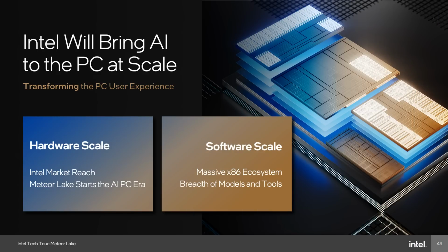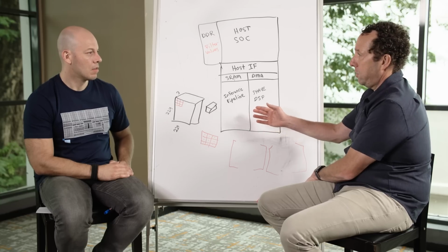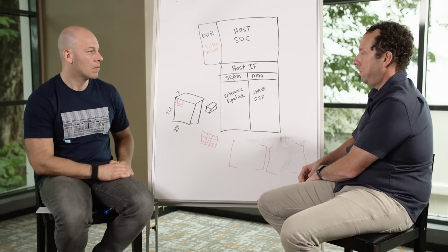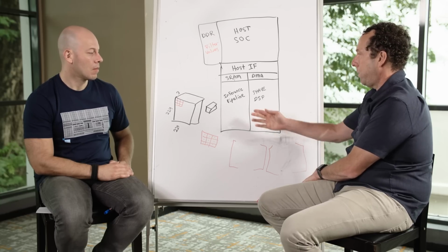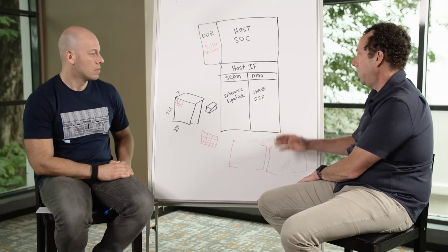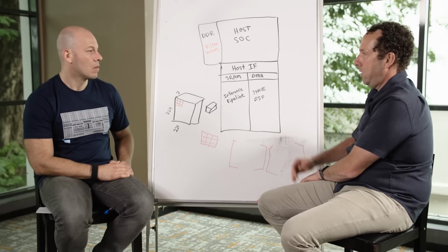Let's say a new paper comes out and there's a new network architecture. We'll take that and analyze it. We do a simulation to see what our performance is. And then we look to see what's the bottleneck? What's taking the most amount of time, or maybe are we not having good enough efficiency? So then we look to see, should we add some new fixed function hardware in the inference pipeline, or should we tweak some of the way that we're processing data in the inference pipeline, or should we add new instructions in the SHAVE DSP?